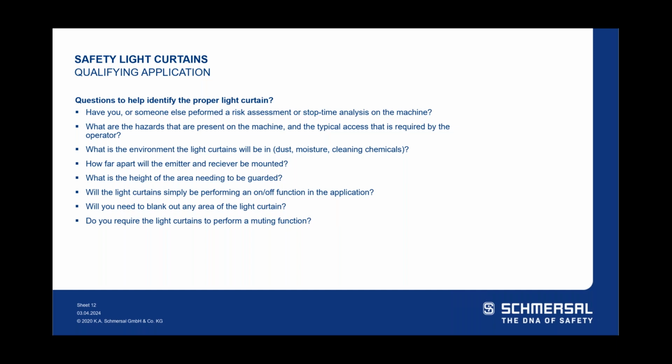This, again, could be really important. You don't want to order and purchase super expensive light curtains and you don't need the functions that you're given on them. So a good question right off the bat is, how are these going to be used? Is it just simple on-off? Are we going to need to mute something, blank something? It'll lead you in different directions. So it's a good question to ask.